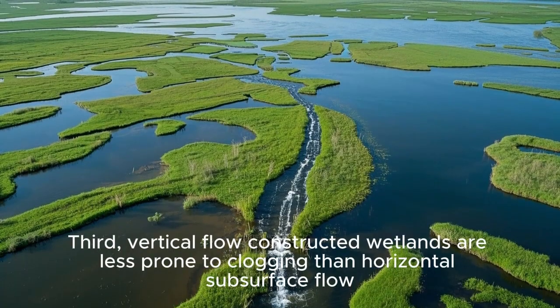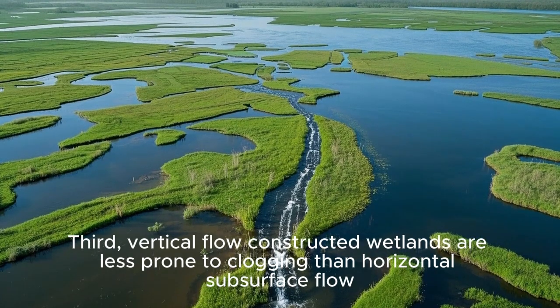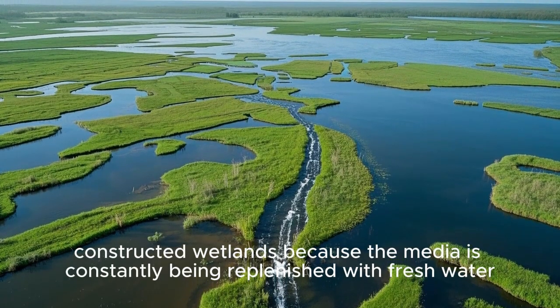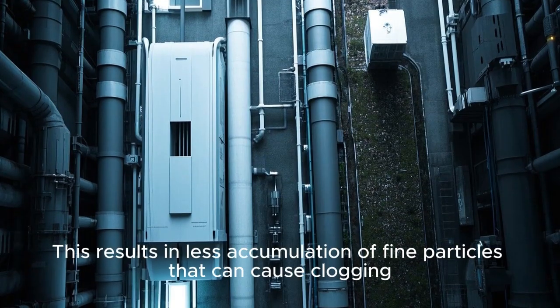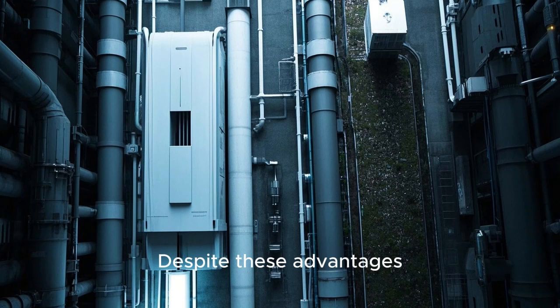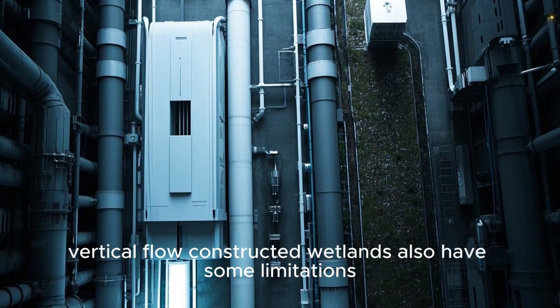Third, vertical flow constructed wetlands are less prone to clogging than horizontal subsurface flow constructed wetlands because the media is constantly being replenished with fresh water. This results in less accumulation of fine particles that can cause clogging. Despite these advantages, vertical flow constructed wetlands also have some limitations.